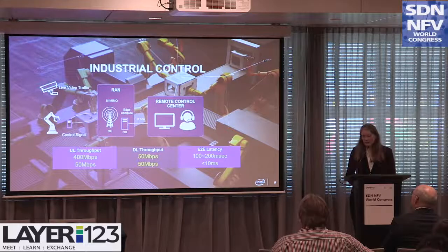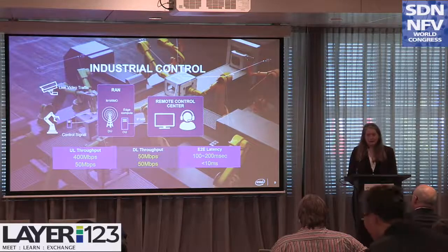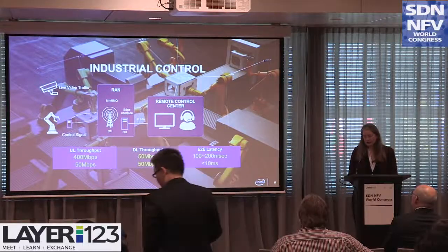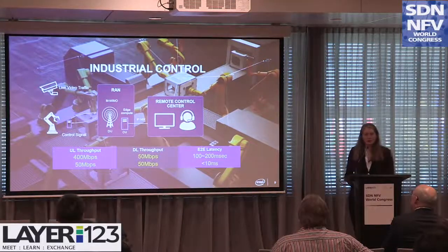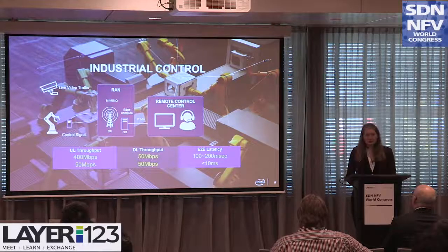So that's got the characteristics of more uplink throughput because we're trying to stream video and not particularly stringent latency requirements. But by itself, it's already quite different from wireless broadband data because most of that wireless broadband today is downlink data dominated. So 5G in a TDD system does give us the ability to switch between downlink and uplink subframes based on the amount of data that we have in each direction.